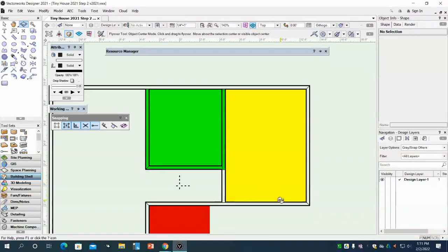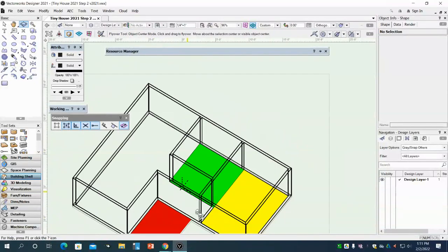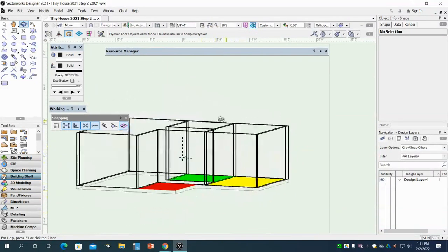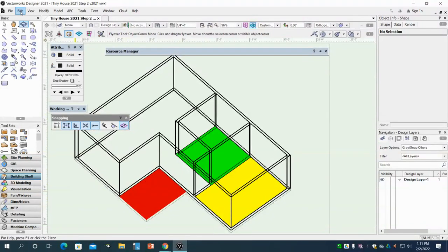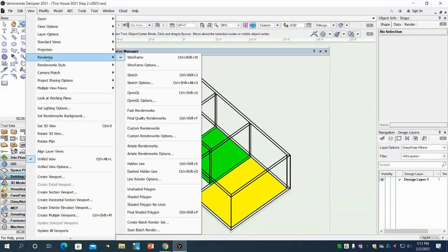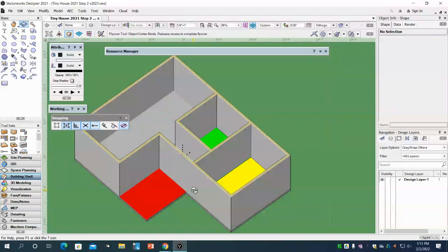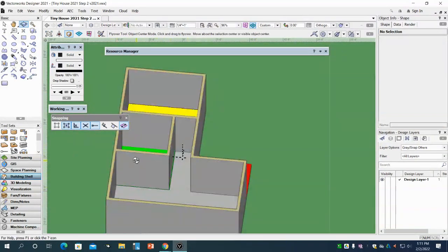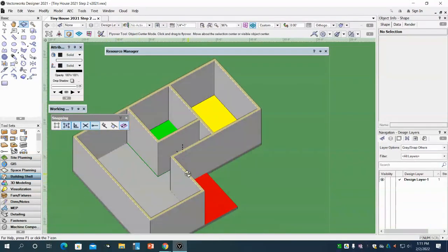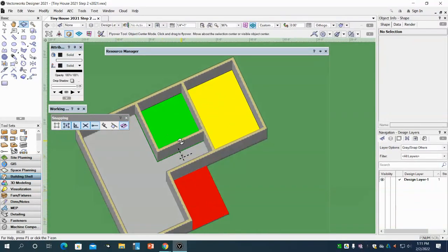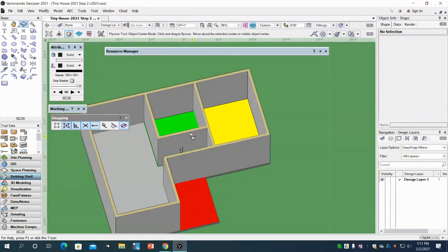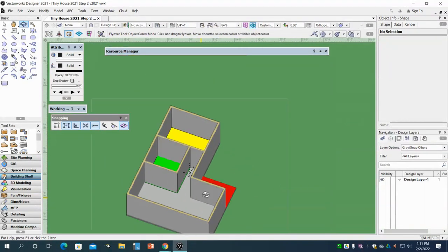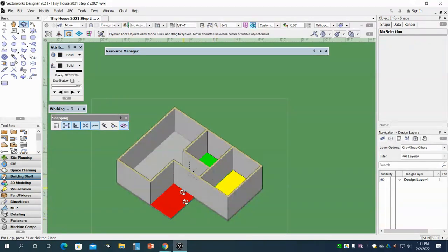Now, like I said, I still have a closet in this area. I need to put in a closet in this area. But if we do the flyover tool, you'll see that my two rectangles move around with my drawing. And I've got the interior partition started, just like that. We don't want to worry about any door openings right now. We'll put the doors in later. If we were to worry about trying to draw this wall over to where the 2'6" opening is, and then a 6" wall for the jamb, we'd end up not having any wall up here above the door. So we'll put the doors in later. For right now, that's how we get started with the interior partitions.